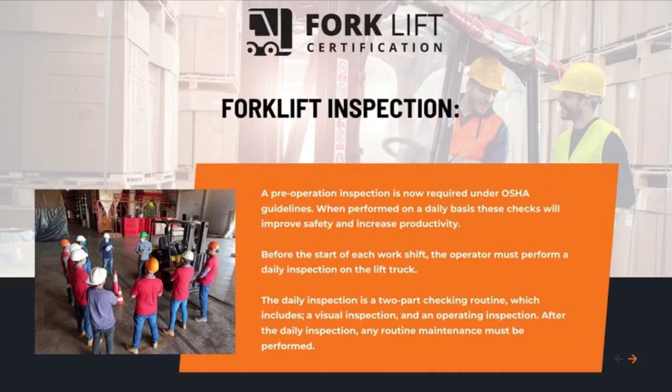Forklift inspection. A pre-operation inspection is now required under OSHA guidelines. When performed on a daily basis, these checks will improve safety and increase productivity. Before the start of each work shift, the operator must perform a daily inspection on the lift truck. The daily inspection is a two-part checking routine, which includes a visual inspection and an operating inspection. After the daily inspection, any routine maintenance must be performed.